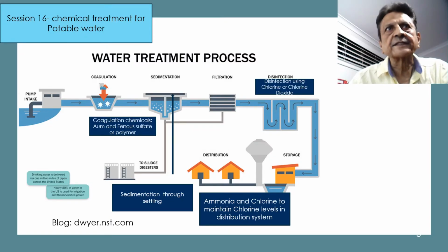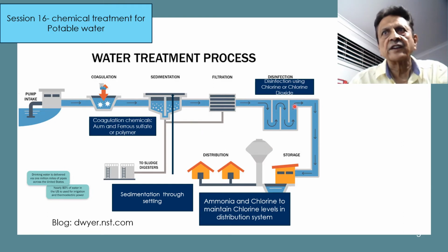This slide represents a diagram of a water treatment process generally used by small commercial or community water treatment. The reason is the fact that the water is generally not of very good quality and therefore would require coagulation and sedimentation, followed by filtration and then chlorination.